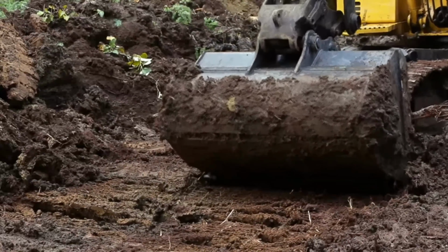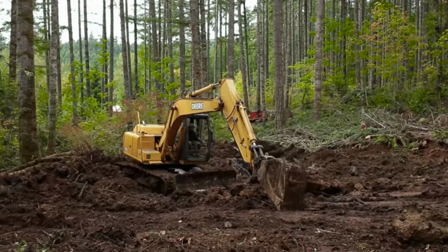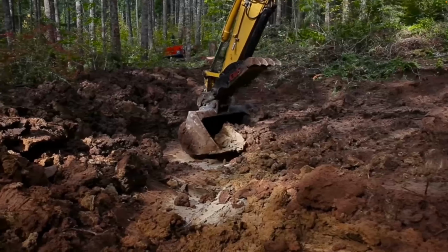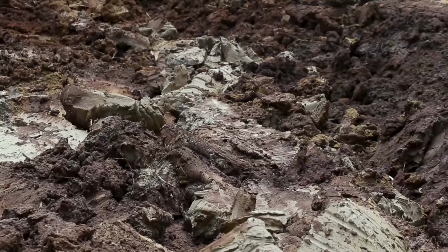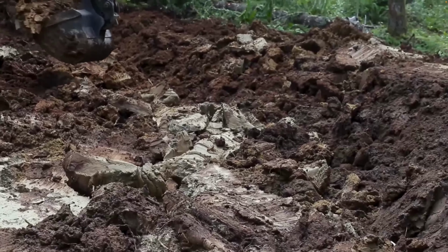So we're excavating down to the point where we have the adequate type of non-porous and strong material to anchor the pond dam into. So we'll excavate that material down until we're at that satisfactory depth, and also relative to the ultimate depth of the pond itself. Then at the bottom of that excavation, we build a little key for us to start piling the best clay, the best heavy, strong material into the core of the dam, and we'll build that up.